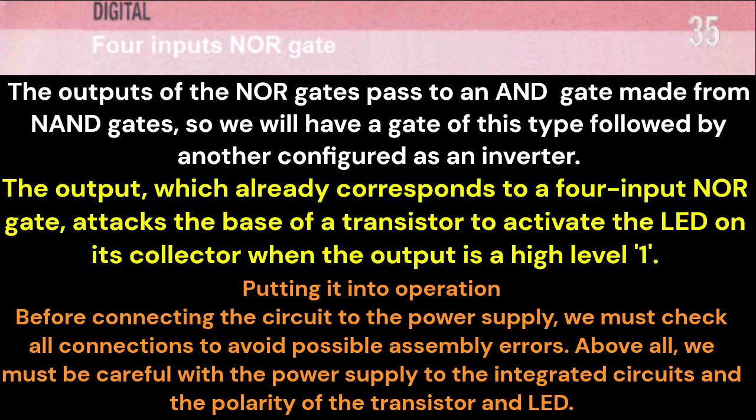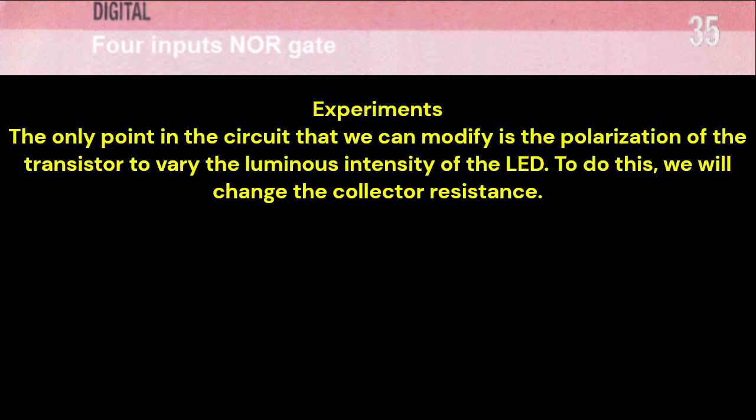Putting it into operation. Before connecting the circuit to the power supply, we must check all connections to avoid possible assembly errors. Above all, we must be careful with the power supply to the integrated circuits and the polarity of the transistor and LED.